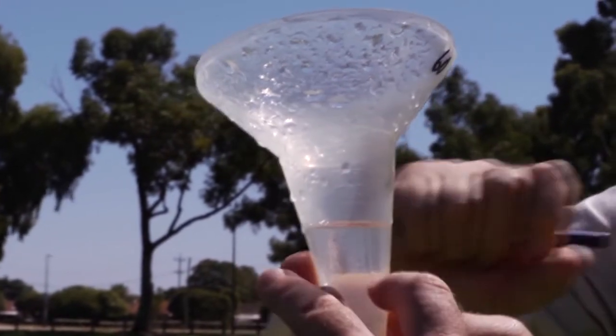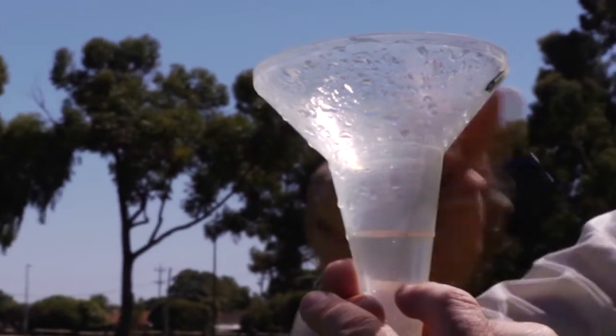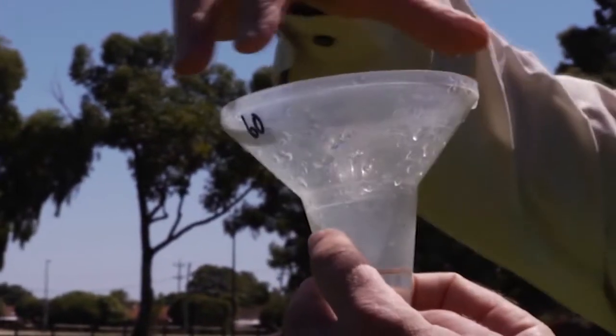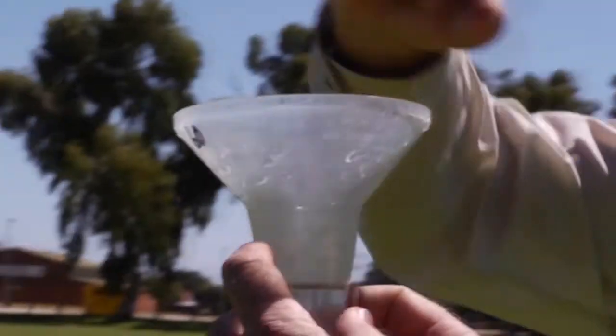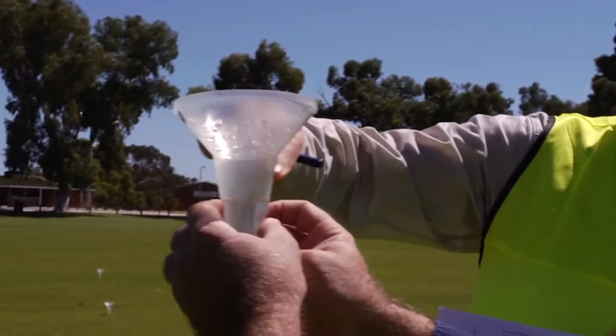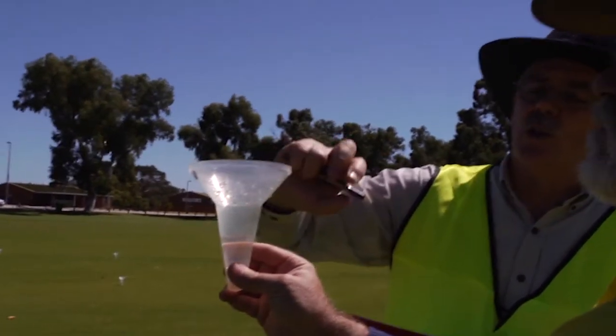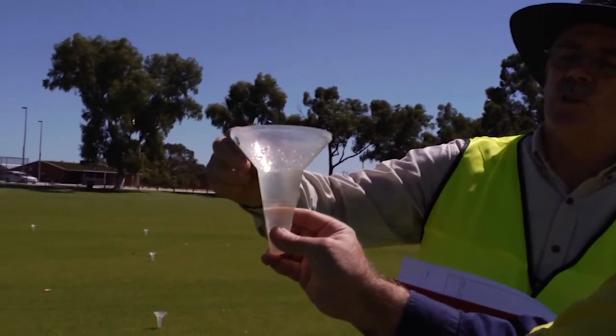So if you want to do a quick test for what the application rate is, you've got millimetres already on there. So they're specially designed for this thing. The beauty of having a catch cup like this with the wide throat area and the narrow calibrated receptacle area is that you've only got to run the system for 10 minutes and you get a reasonable reading.